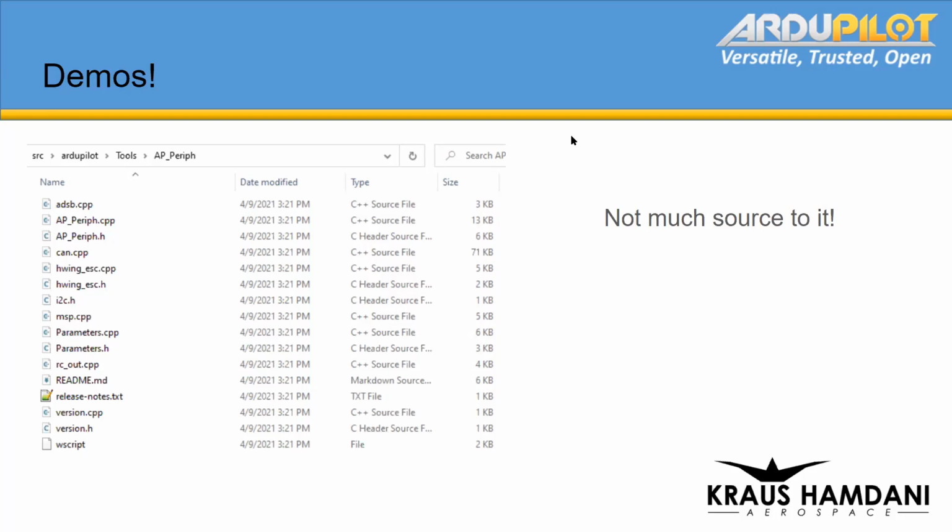And that information is basically all of ArduPilot's state, really. So one limitation we have is that all this data has to get squeezed through the UAVCAN port, from the vehicle to the node. It has to tell it everything. And there is information like that, essentially your GPS information that gives you your location, heading, and all that sort of stuff.